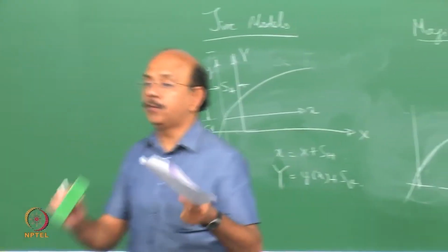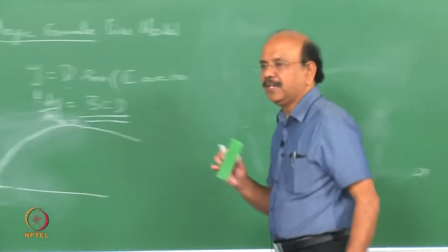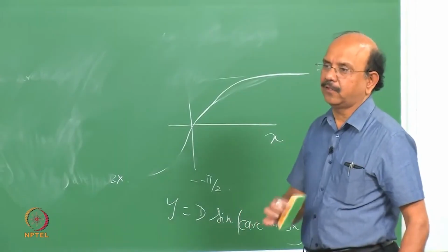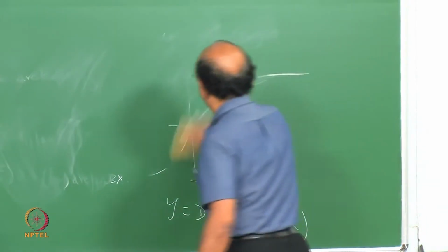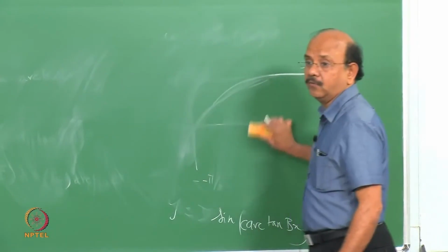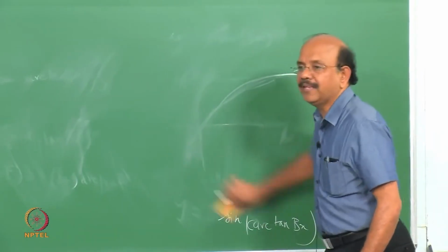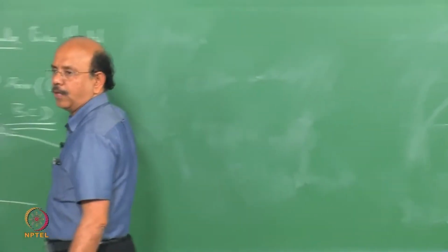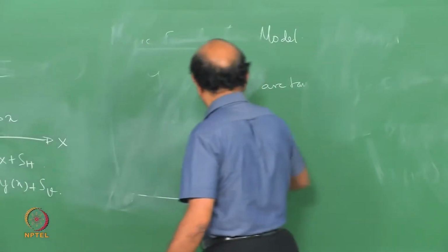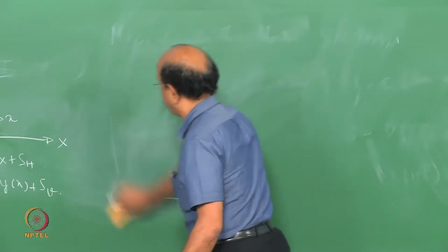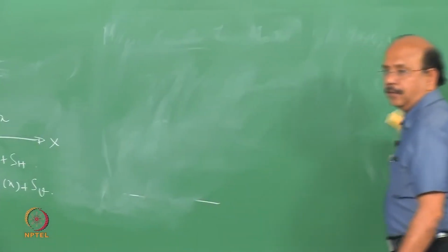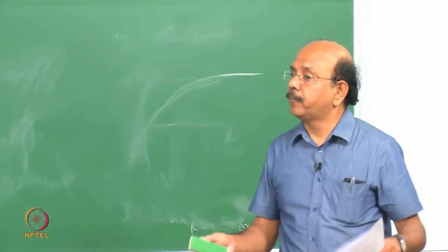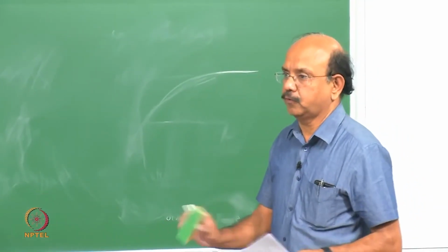We will first develop a simple mathematical model to enumerate what things act when I have combined cornering and braking, and then we will indicate how it is done. But even today, most people don't do combined cornering and braking, and all these formulas that are used even today are only for a decoupled longitudinal force and decoupled cornering forces.